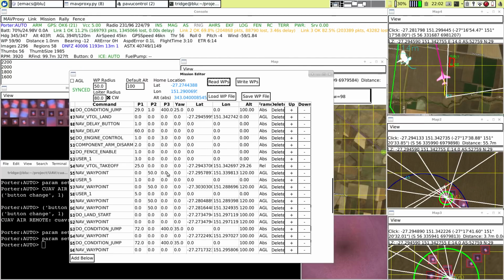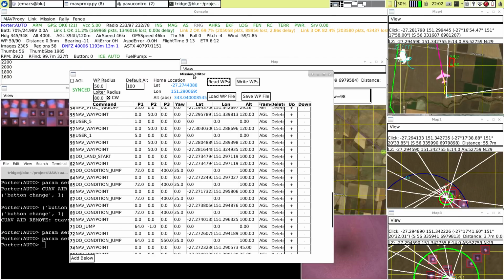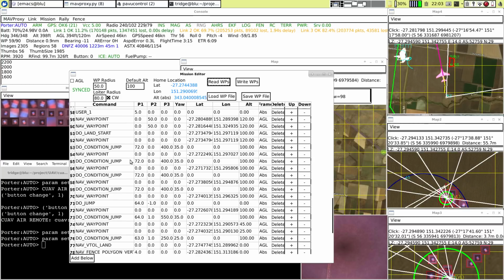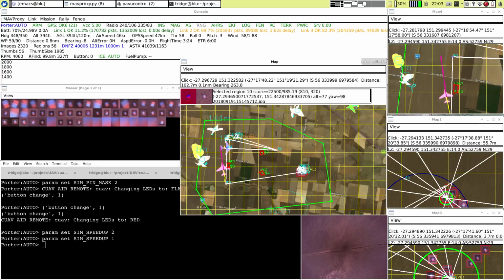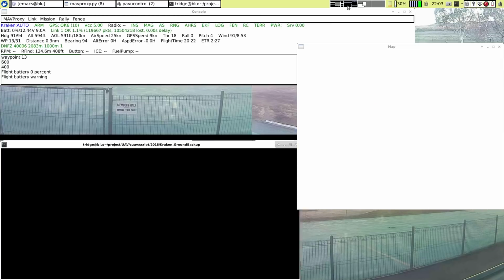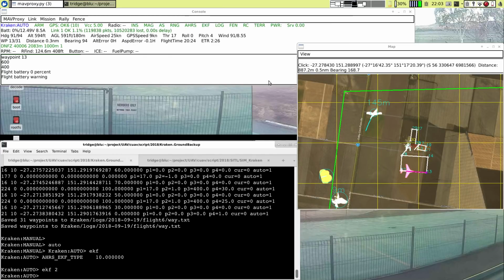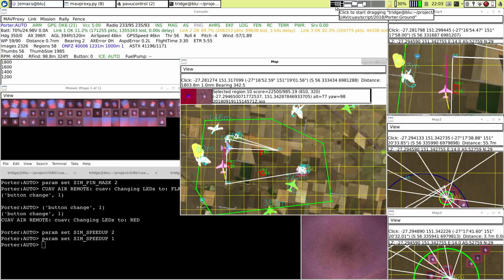Nope, hasn't sent a recall Kraken. Have I got it set up correctly for this one? What waypoint is it heading towards? 59, waypoint 59. And yes, there should have been a recall Kraken being sent out there as it's heading towards waypoint 59. So that is something that I will have to have a look into and see why it's not recalling the Kraken. The Kraken will automatically land based on its flight time, but it'll be rather tedious if the Kraken is up there for 30 minutes while the porter is...